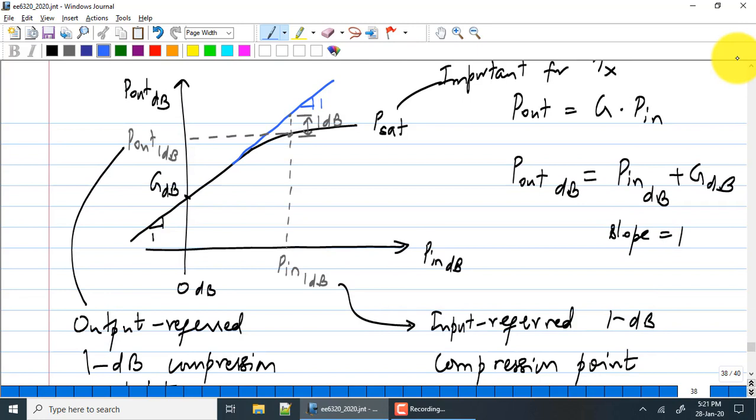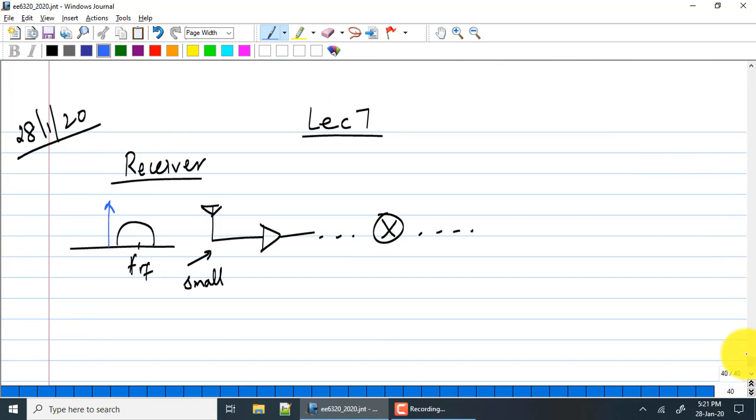If you look at the relative value of the other harmonics versus your fundamental, it will give you the harmonic distortion. What we are going to do is something totally different. I am now going to take this system and put in two tones, and by convention these two tones are equal amplitudes, spaced apart by some small delta omega.